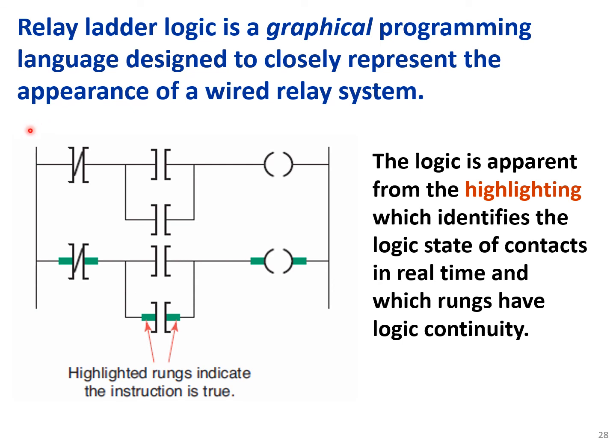Relay ladder logic is a graphical programming language designed to closely represent the appearance of a wired relay system. We have repeated this sentence many times. Here you could see one example of these programs. The logic is apparent from the highlighting, which identifies the logic state of contacts in real time and which rungs have logic continuity.